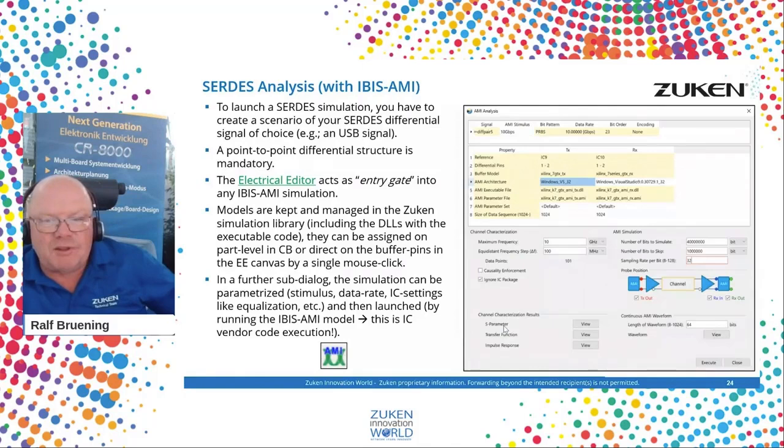to parameterize the simulation, where you can define what is the bit error rate, what is the coding scheme, what is probably the amount of bits which you have to skip. So I did a project for Xilinx Kintex 7, where Xilinx is requiring the first 256,000 bits should be thrown away. And then the valid process did start.